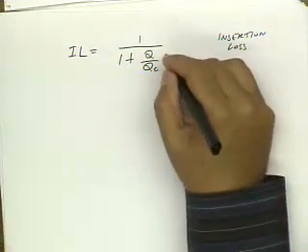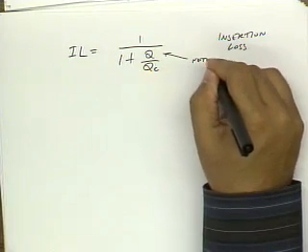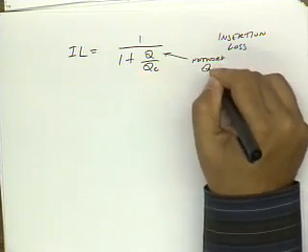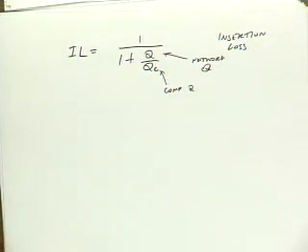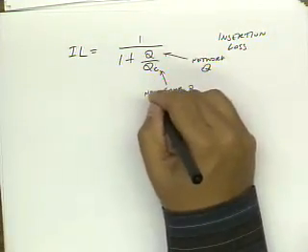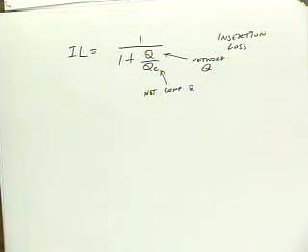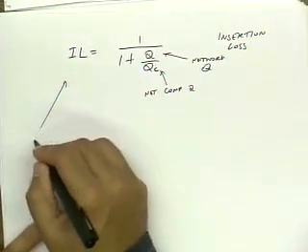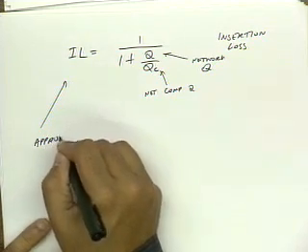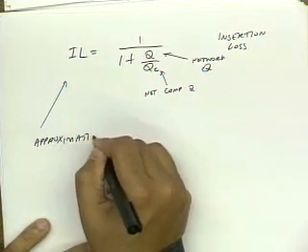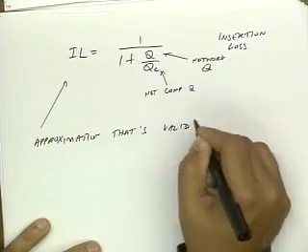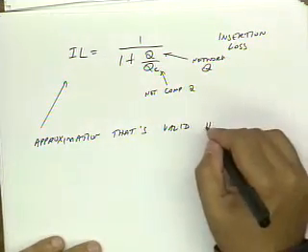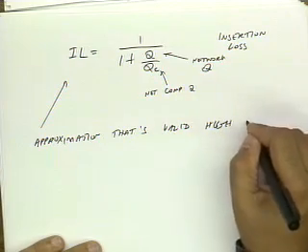Okay, so this is the network Q. This is the component Q. It's the net component Q because we're using both inductors and capacitors. Okay, now this is an approximation. And it's more and more valid as we go to a high Q assumption, to a high Q circuit.